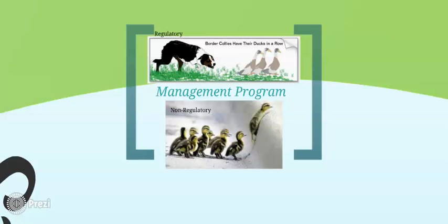There's also non-regulatory programs. These include public education, best management and pollution prevention practices, groundwater monitoring, household hazardous waste collection, water conservation programs, written agreements, and property purchases. These types of non-regulatory programs are best to control current potential contamination sources within your zones.